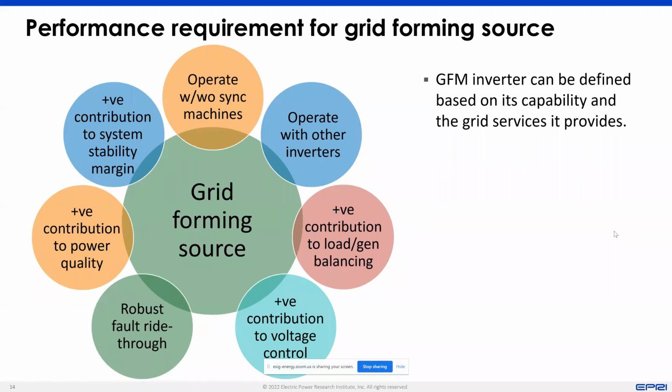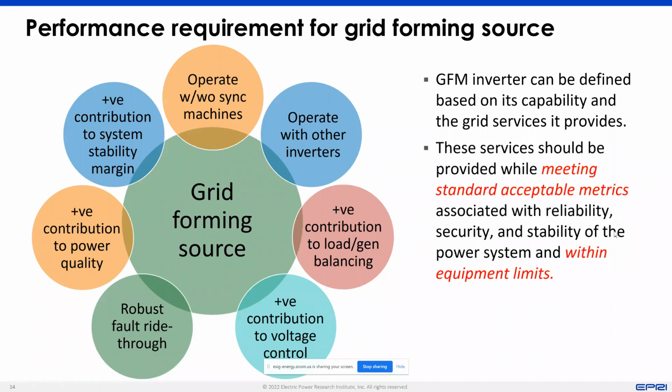It can operate stably when connected in parallel or alongside other inverters in the system. It has to positively contribute to both load and generation balancing, positively contribute to voltage control, work towards improving system stability, have robust fault ride-through, and so on. At the same time, it does all this while respecting the equipment limits.